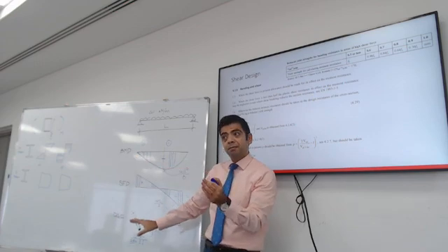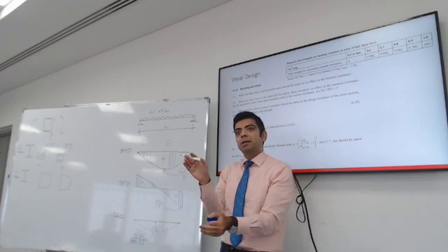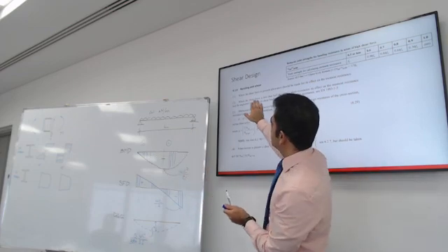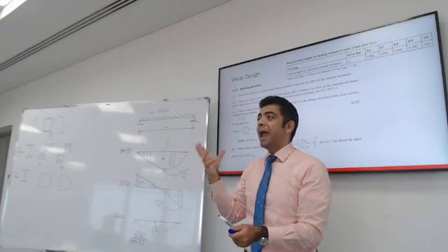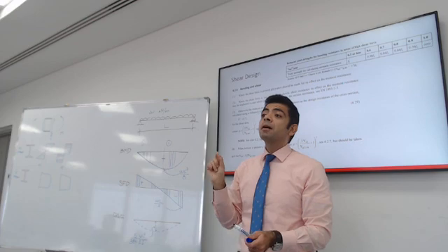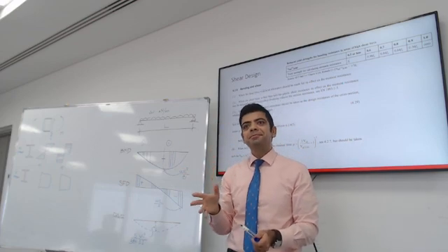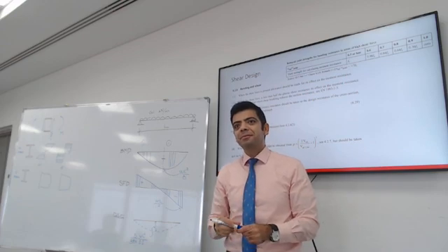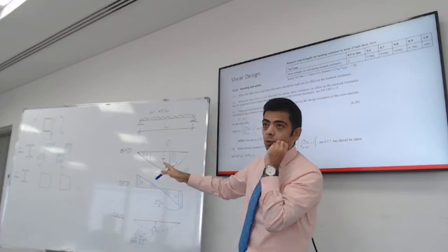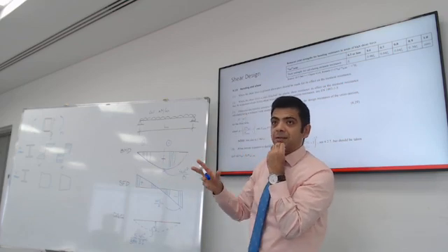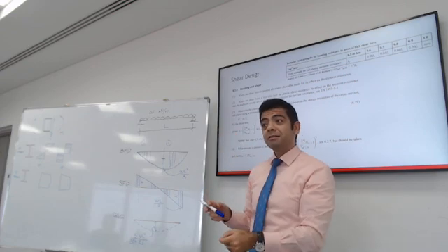So what if you're designing a section that has maximum shear and maximum bending? This is what this equation is about. It's called bending and shear. If a section has bending and shear, can you think of a situation where a section has maximum bending and maximum shear? I'm curious if you can think of a scenario. Distributed load with point load. Yes, that's a good example.